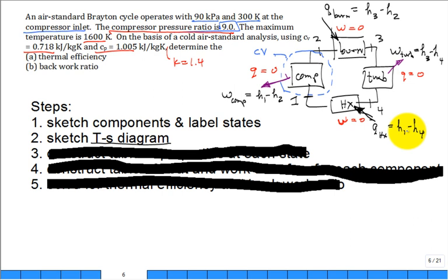Okay, you do a second law analysis for each of the components. Maybe we write it out for the compressor. Maybe it's been a while. So for the compressor, you're going to have 0 is equal to the mass flow rate times S out at 2 minus S1 in, plus any Q coming in divided by some T_B. But guess what? Why is that equal to 0 for the compressor? No heat transfer, no entropy transfer with the heat coming in.